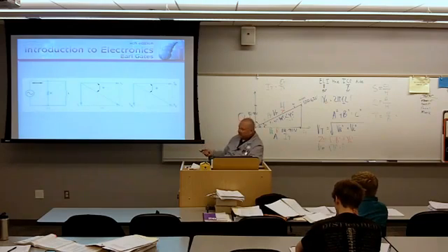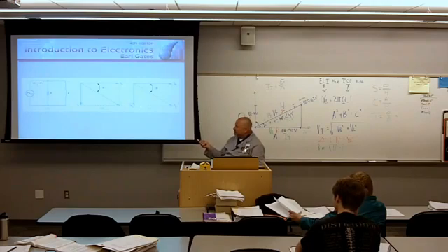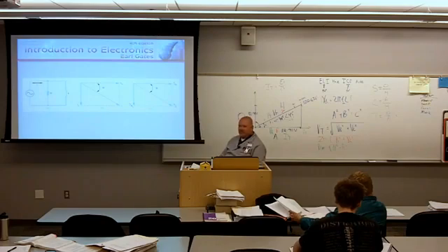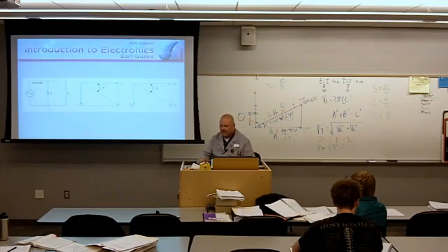In a parallel circuit, the book shows you this technique here. The reciprocal of reactance, the reciprocal of resistance equals the reciprocal of impedance. My recommendation is you don't do this. My recommendation is you don't use this formula because the reciprocal of inductance and the X sub L, there's a lot of moving parts to this. You're probably going to slip a finger in a calculator and get a wrong answer. If that's the case, how can you calculate out impedance in a parallel circuit?